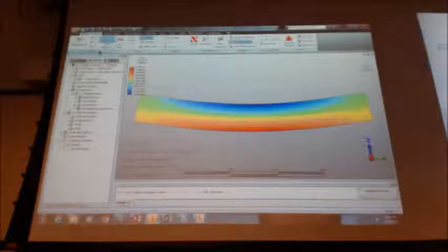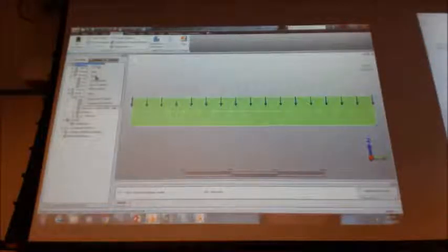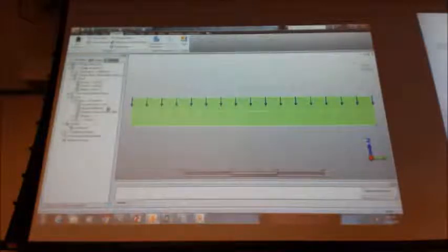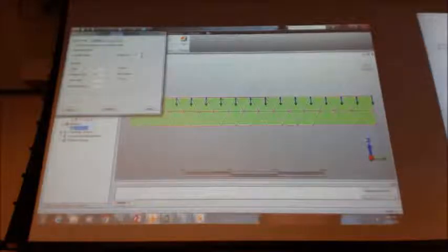I forgot what the other thing was I was going to show. Oh, so now once you're creating your new scenario that you're going to change and add more. So what was this one? So if I edit my mesh, right? So this is one thing that I haven't figured out how to make better yet. So we're going to make our mesh height 2.5, so that should give us 4 rows.